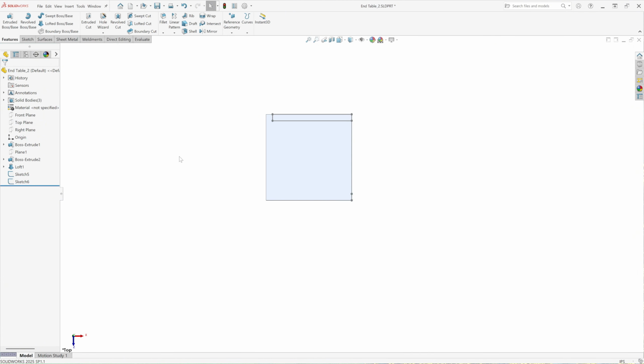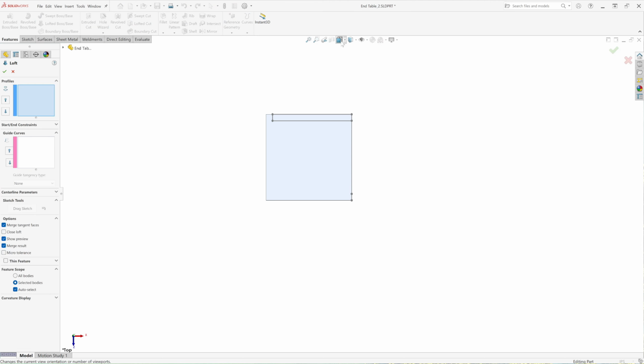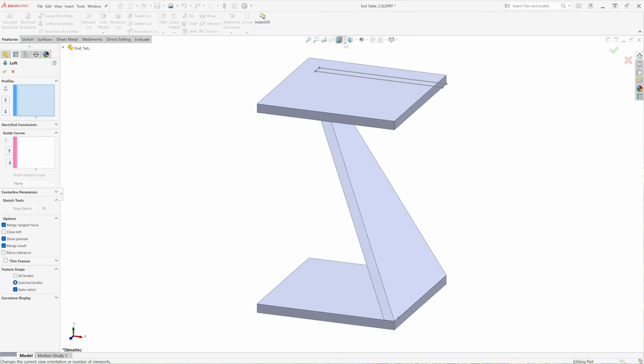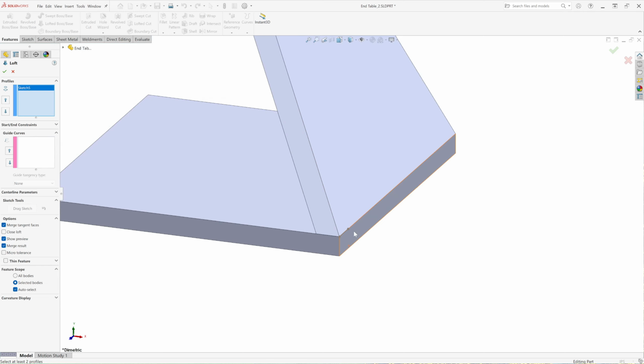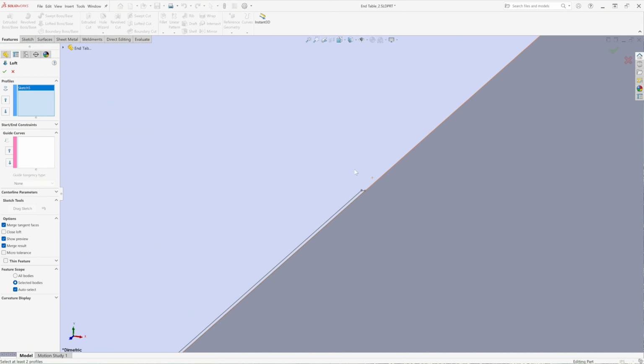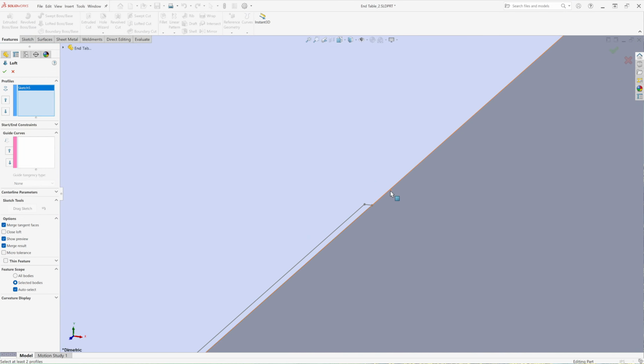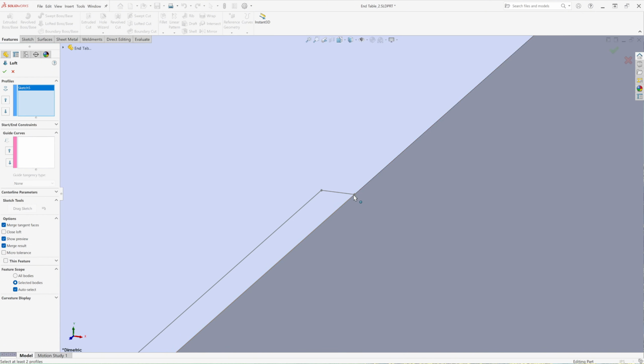So now I'm going to do a Lofted Boss base again. Features, Lofted Boss base. I'm going to my dimetric view. Again, I'm going to choose this point right here, not the edge, the point. And I'm going to zoom into this tiny rectangle here and choose that. If it highlights that line orange, that's the edge. We want the point, that dot. So the point to be orange. There we go.